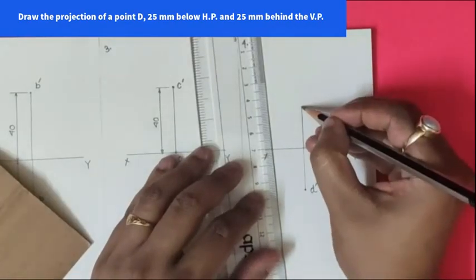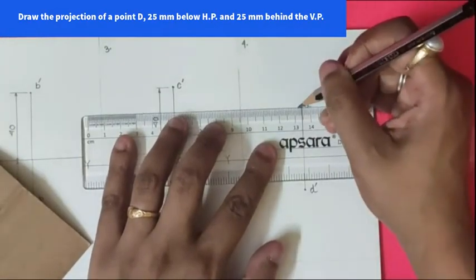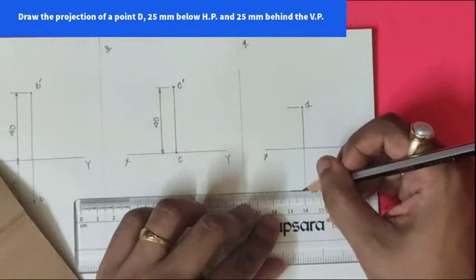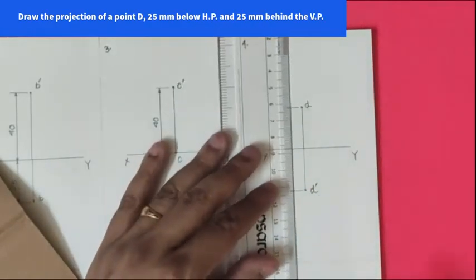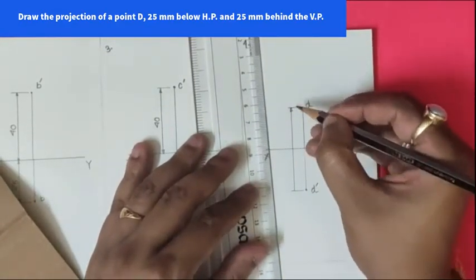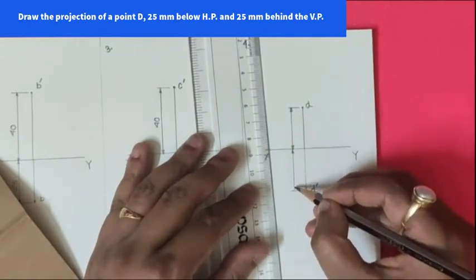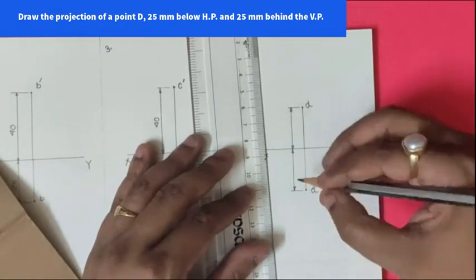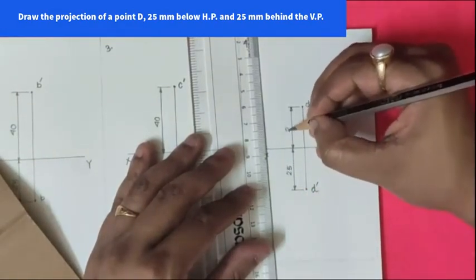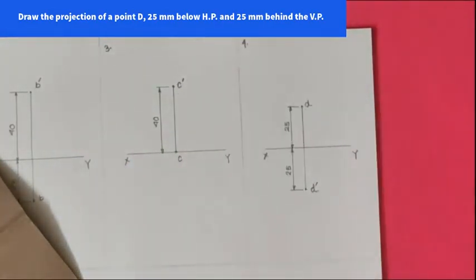So this is your top view. This is d. Let us start the dimensioning. You have to follow the aligned system of dimensioning. That you have to remember. Don't use the unidirectional system. And never give any mm or centimeter here. You have to write just above the title box. So this is your 25 and again this will be your 25. Clear?